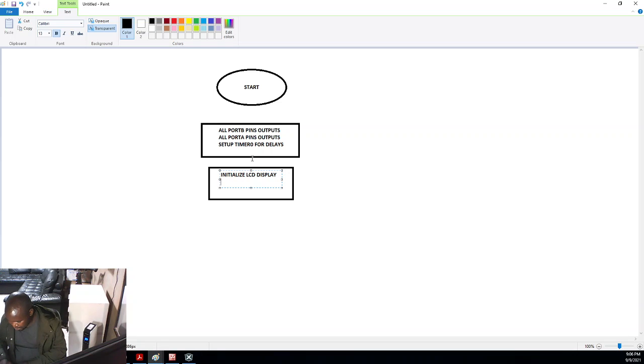Now here we'll be using 8-bit mode to start with. That's the most important thing I need to inform this display for this particular example. I can go further and inform it to increment the cursor every time I write a character. Every time you write a character, it goes to the next address so that it doesn't write on the very same address all the time.